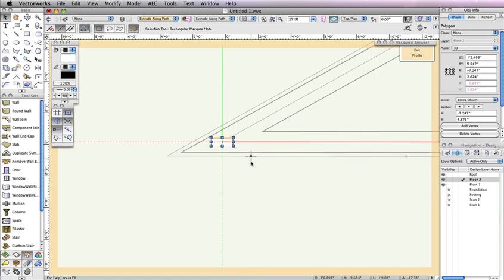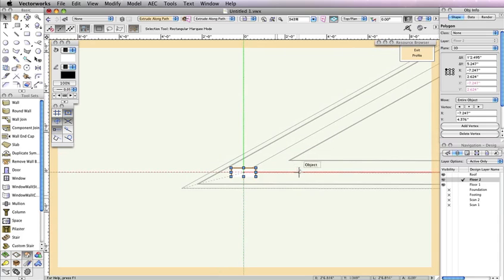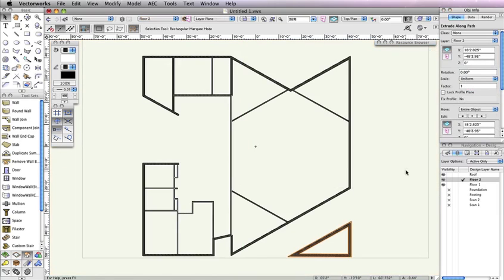So double-click the extrude along path, choose to edit the profile, and click OK. Select the polygon again, and in the Object Info palette, set the top left point in the box control matrix. Additionally, set the X field to -1.25 inches and the wide field to 0.5 inches. Once complete, click Exit Profile to return to the drawing. Now, with the newly created extrude along path still selected, set the Z field to -1 foot in the Object Info palette and press Enter to lock in that value.